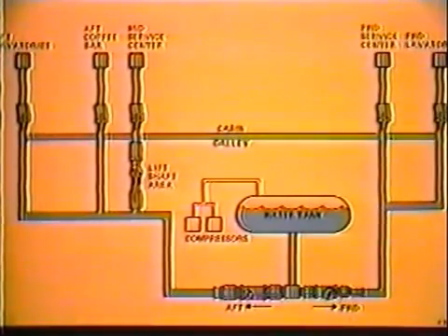The water distribution lines are protected from freezing by dual-element water line heaters in the unheated areas. If one of the heater elements in the water line heaters fails, the other heater element will continue to provide adequate heat.